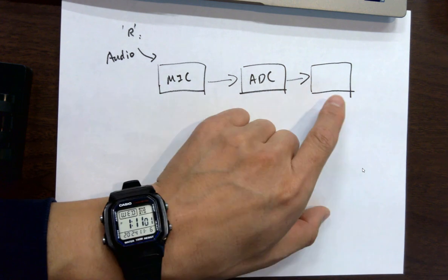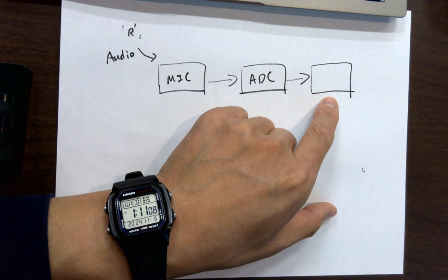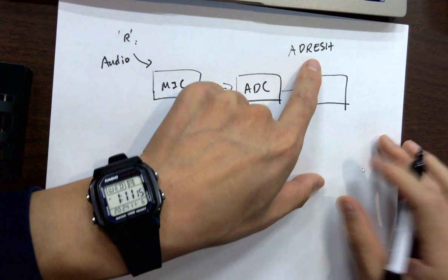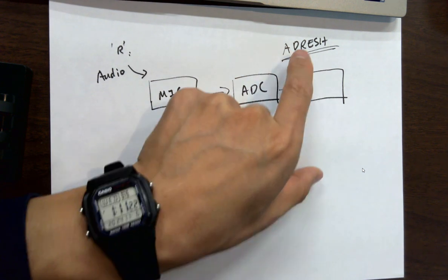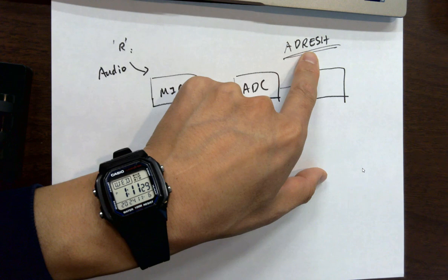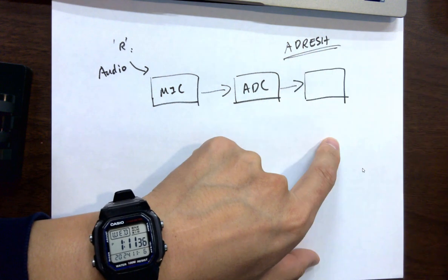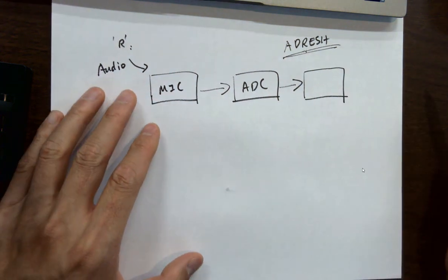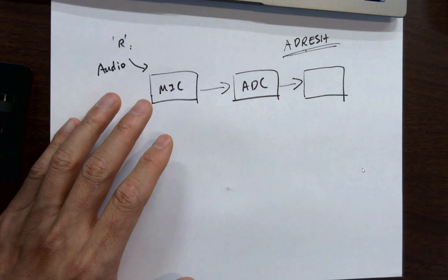So what are the digital signals? Bytes, right? Remember where these bytes are stored? The ADC result register, something like this, right? Maybe I spelled it wrong, but anyway, it's a register directly connected to the circuit block inside the chip. So the ADC's converted data is already stored in this register. It's designed by the digital designers at Microchip, so we're not able to change it. So eventually you read from these ADCs, okay? And how many times do you read before you write it into the SD card? 512 times, because every time it's writing and reading in blocks, and the block size is usually 512 bytes.